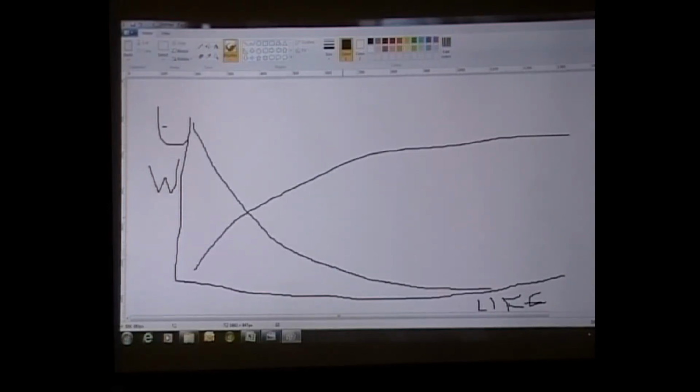When you go into a manufacturer's catalogue, and it used to be quite cynical, they would say, this LED is good for 100,000 hours. So you get your calculator, at 24 hours, we're going to run it 30% of the time, 10 years life. So you start seeing manufacturers saying 5 years life, 10 years life on stuff. But that was at 20 degrees. You can't run an LED at 20 degrees. You turn it on, it goes up to about 40 or 50. So it was rubbish. So actually now they've all agreed to publish the life figures at 80 degrees, which is a reasonable thing.